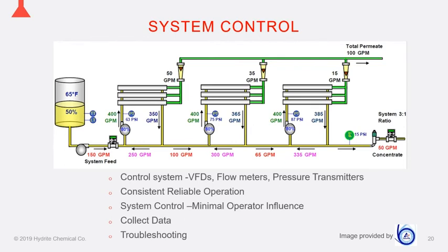And then you can see we only permeated 15 gallons a minute. And that again is because our solids going in is 11% solids, higher osmotic pressure, same baseline of 15. So our driving force is the same. So it's harder for those water molecules to pass through because we didn't increase the pressure to push more through. But you can see the composite total of the 3 loops is 100 gallons per minute. And then from there, you can see the 50 gallons per minute coming out as our concentrate, which is exactly what we saw on our first slide. So that's our balance there.